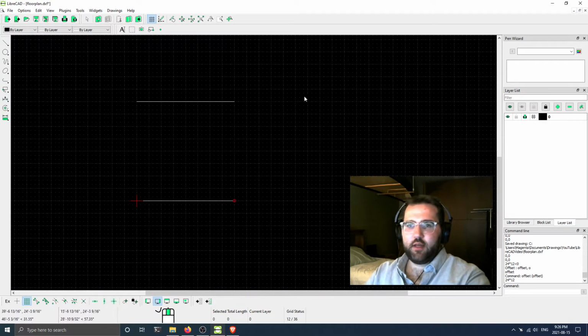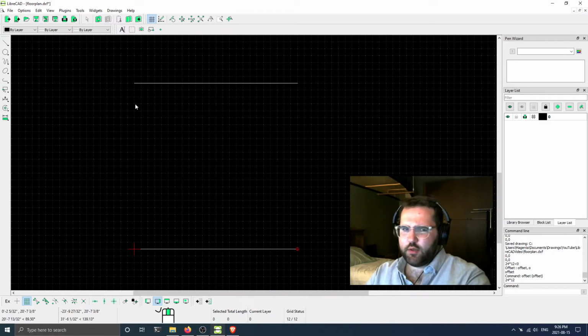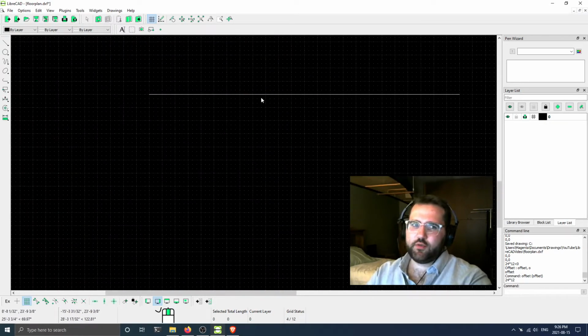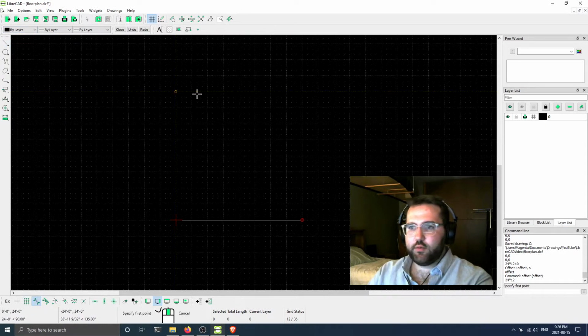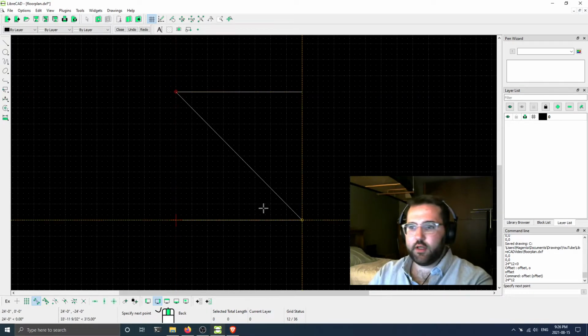So anyways, now that we have this line made, I'm going to connect this side. So I've been using grid snap, and you could use grid snap in this particular case because the endpoints do align with the grid. But say that they didn't, I could turn off grid snap and actually turn on endpoint snap at this point, and go back into my line tool, select 2 points, click there, and click there, and you can see that the cursor or crosshair is jumping from the endpoint of one line to another line.